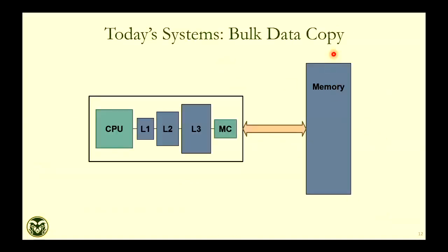So how is copying done in today's world? Suppose you want to copy this white row to a dark row like this. You know how it is done in today's computing stack? First you will get this data byte by byte to the CPU. In today's DRAM, there is no way you can copy from one row to another row. You take the data to the CPU and write it back. It's a huge bottleneck. Then all this computation benefit will be gone if you do it like this. So this is how it is done today, and then you'll copy that.